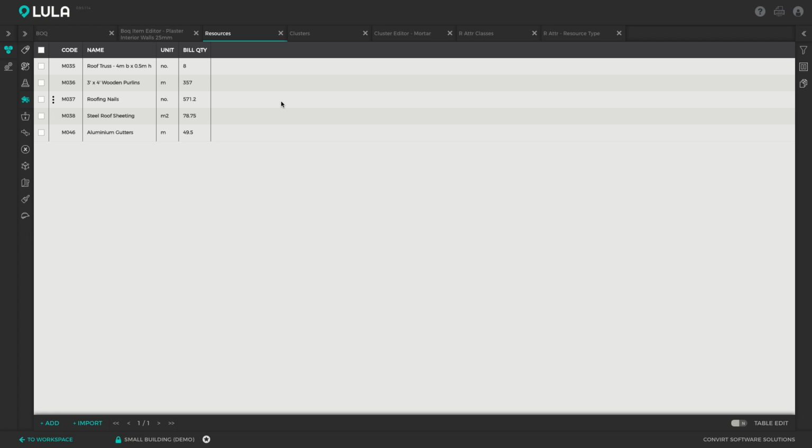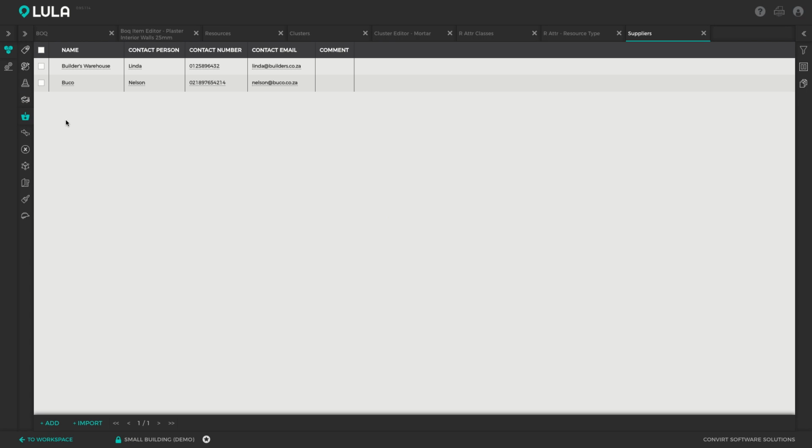Okay. So let's say we've sent this report off to the suppliers, and we've asked those suppliers to send us quotes back. We can then adjudicate those quotes, compare the quotes in the system, apply the cheapest quote and use it in our estimate. I've set up 2 suppliers, just for the sake of an example, called Builders Warehouse and Buco. And I've set up a supplier adjudication, which is where we compare the quotes from suppliers. I've set up an adjudication for roofing materials.